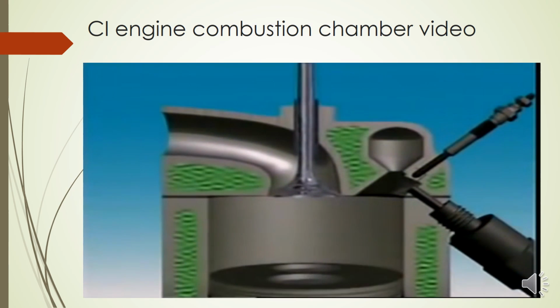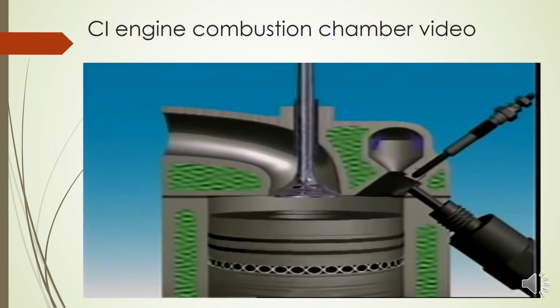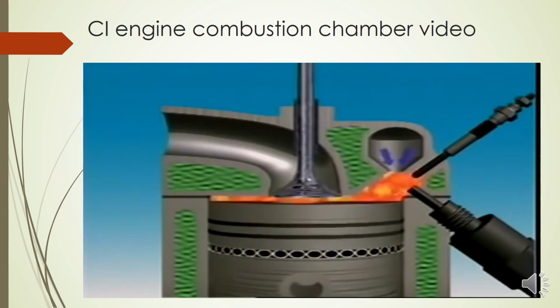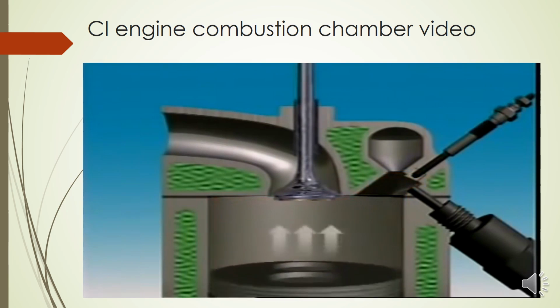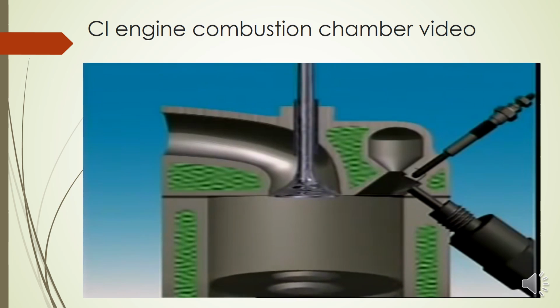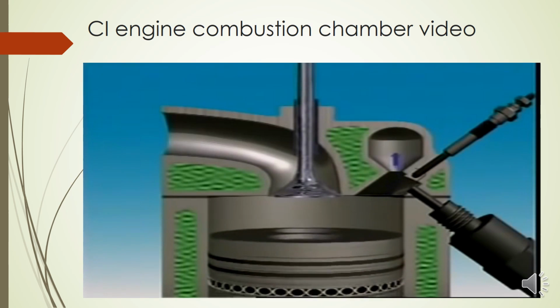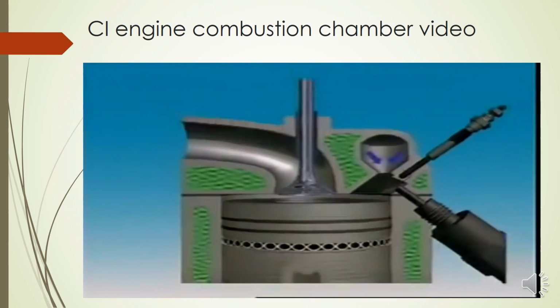And this is a pre-combustion type chamber. This combustion chamber is divided into a main combustion chamber and an air cell joined by a throat. The injector is in the throat. When fuel is injected, combustion is initiated, and the pressure forces air to flow from the air cell into the main chamber, where it mixes with fuel from the injector. The rush of air from the air cell produces a rotary motion of gas in the main chamber, which helps make combustion more efficient. So like this you can find some videos on YouTube.